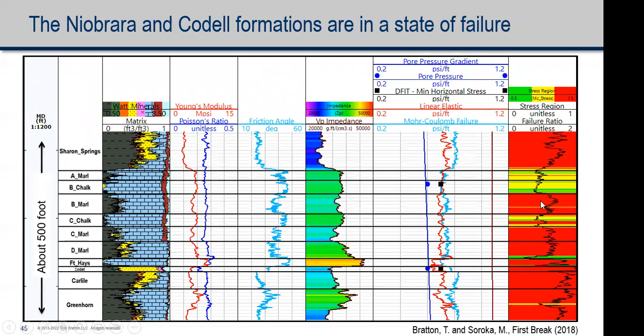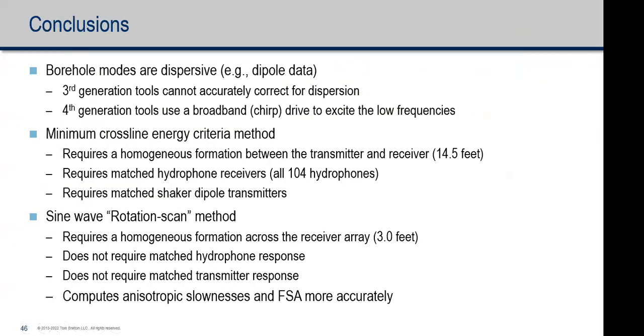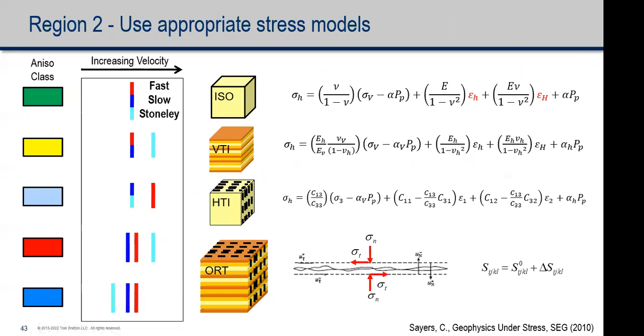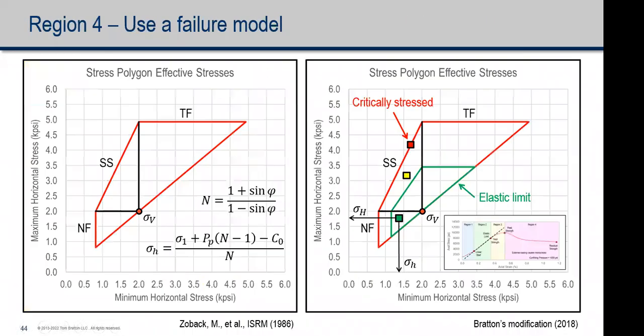And in those cases, you're absolutely correct. This linear elastic theory is inappropriate, and we need to be using this critically stressed approach. Now it's the friction angle and perhaps the compressive strength that governs the stress in the earth, and elastic properties at that point are irrelevant.